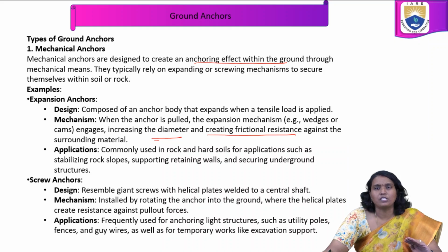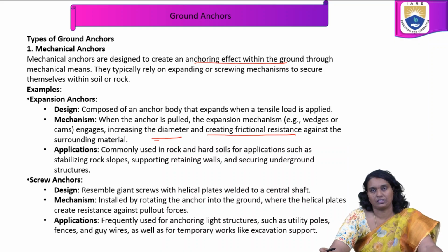We use expansion anchors in rock and hard soils for applications such as stabilizing rock slopes, supporting retaining walls and securing underground structures.